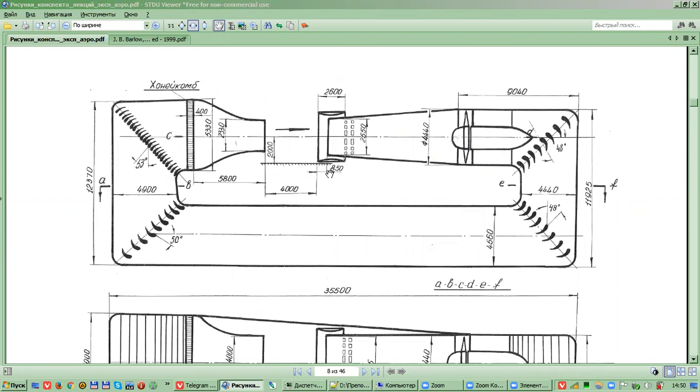For example, the moment that acts on flaps is sometimes very high, and the servo cannot work with these loads and breaks down. And sometimes it's just fixed by a screw.